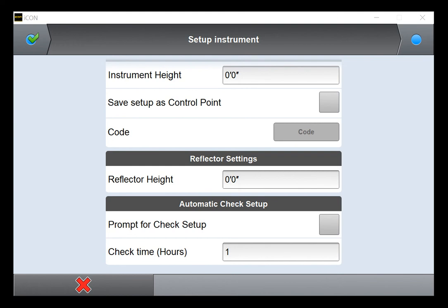If you mistakenly continue laying out without following these instructions, you will find errors later, and not only will you have to lay those points out again, but if your ITR crew has been installing right behind you, they will have to pull all the components they installed and reinstall them. If you don't catch the errors before concrete is poured, you will be chipping concrete later.